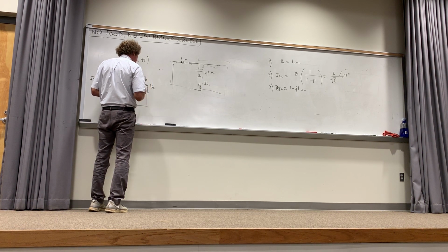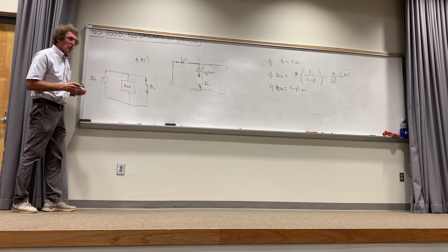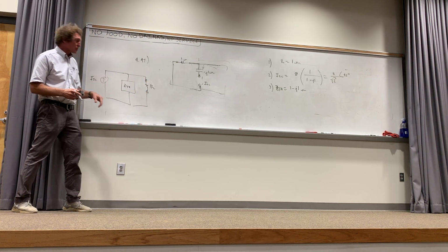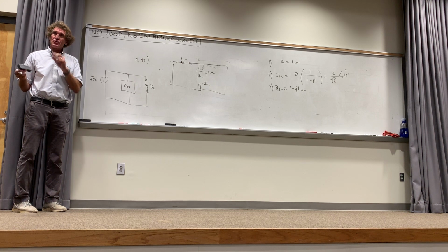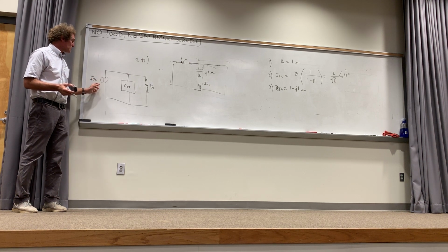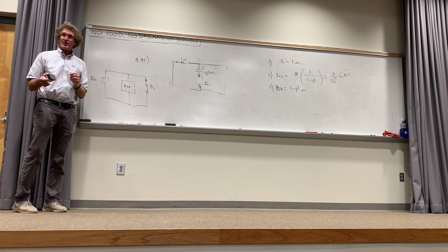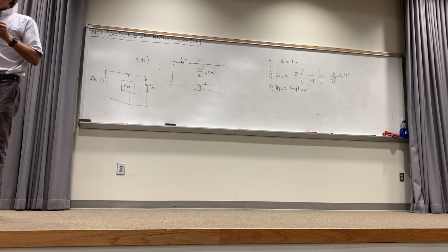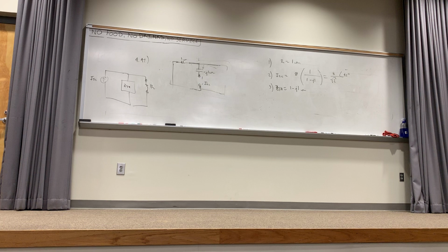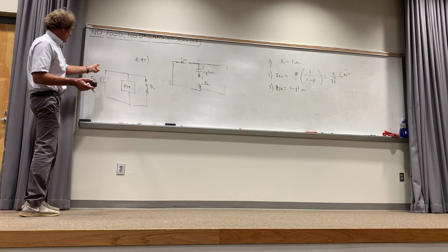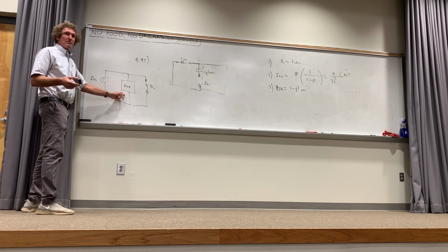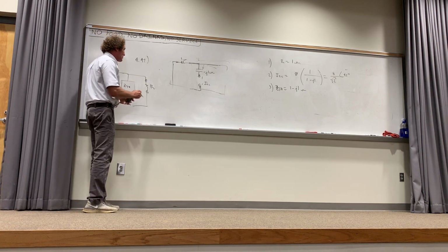And this is the place where now I could put in any load there, and this part of the circuit is effectively replaced by 2, and only 2 things. It's going to be a source current and an impedance in parallel with it. Follow me? With a Thevenin equivalent circuit, once you took the load off, you replaced it with a Thevenin voltage source in series with a Thevenin impedance. Here, it's going to be a Thevenin current, I should say a Norton current right here, short circuit current, in parallel with it, and we want the voltage here.